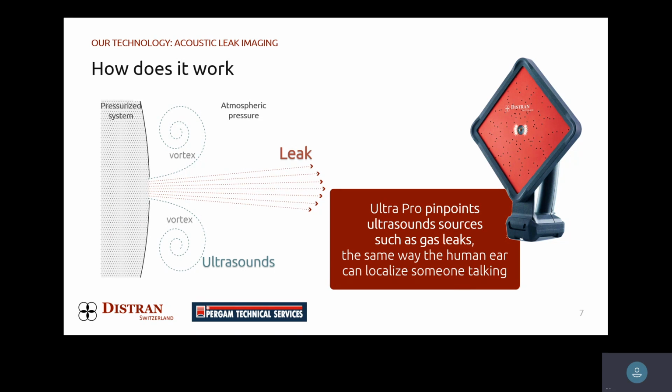The way it works is that we have a difference in pressure between the inside of the pipe and the outside of the pipe, the ambient pressure. The gas leaks out. Keep in mind, this camera is designed for pinhole leaks. It is not designed for your average mundane larger leaks. We will see those too, but it is designed down to 0.7 psi pressure.